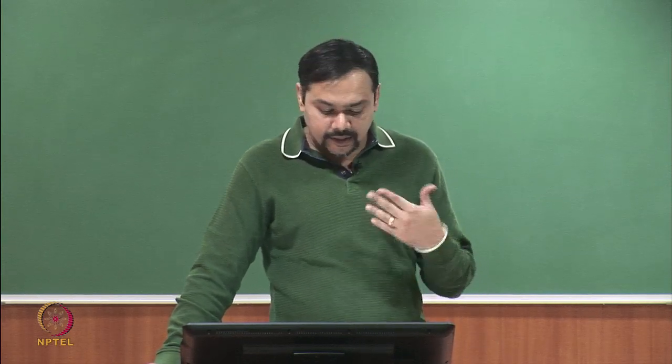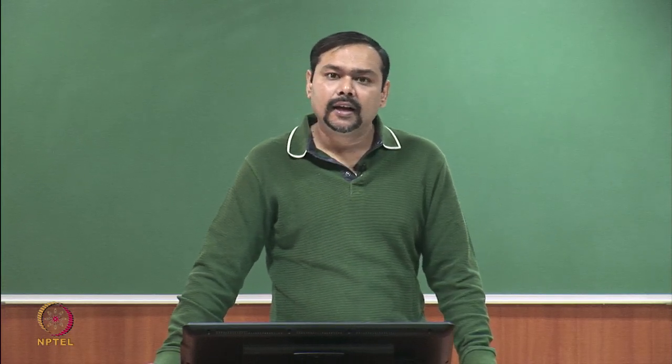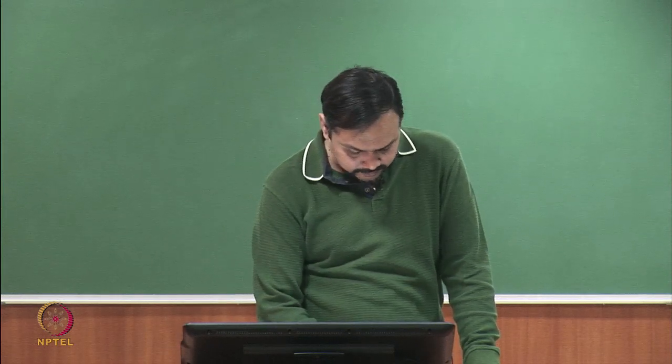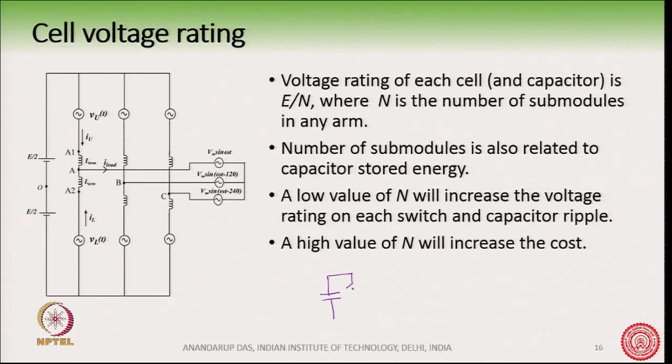Okay. So, some manufacturers use the half bridge like this. Some manufacturers even use half bridges like what we have discussed, like this as the half bridge. But some manufacturers do not have a single IGBT here. They have something like this, there is no single IGBT, but a series connection of several IGBTs.